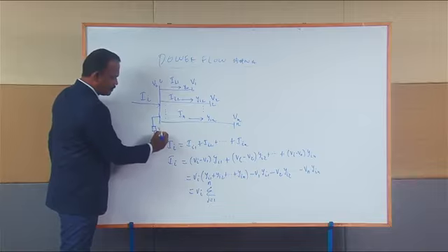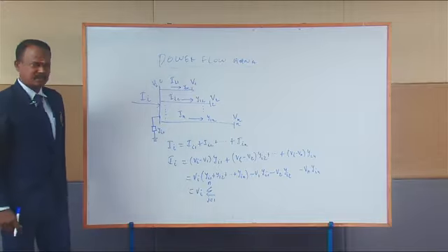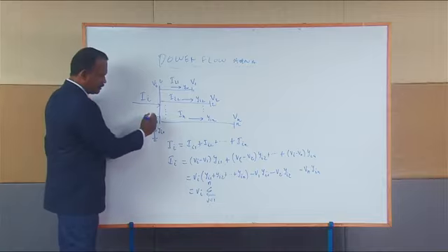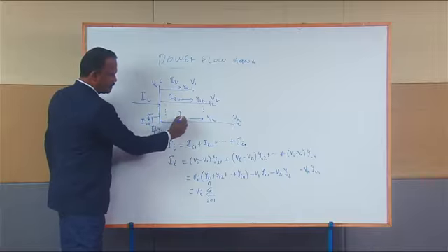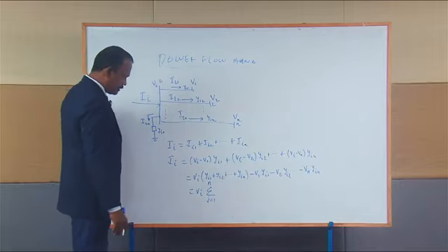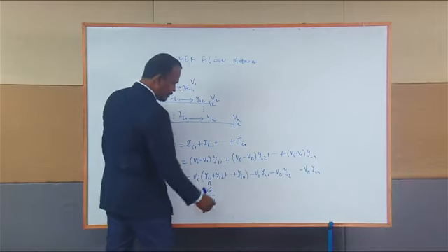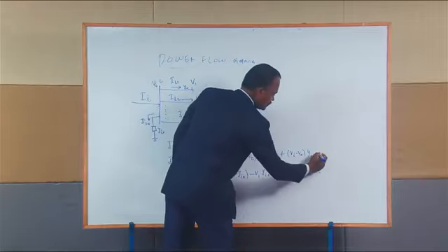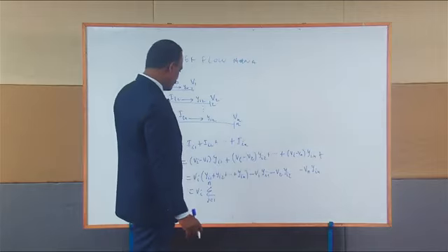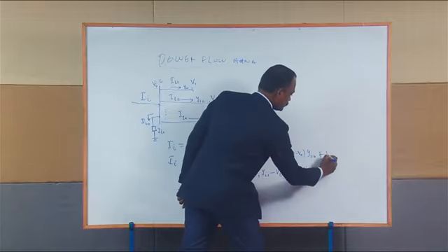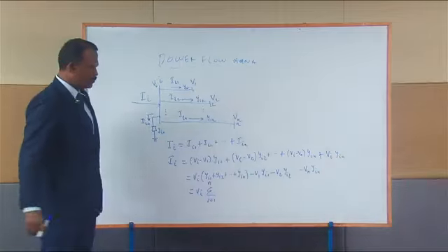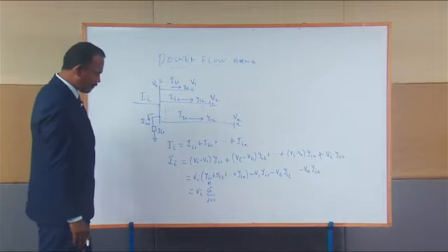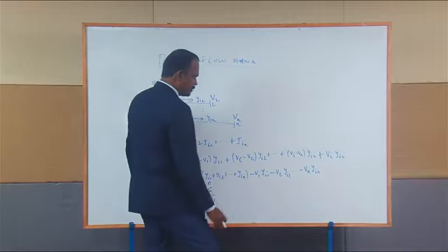Actually, in this diagram we can also include the self admittance of the network. Let us consider the self admittance of this line is yi0, and the current flow in this line is Ii0. Then I'll add one more term here so that this equation will be complete. So this is Vi into yi0, am I right? So I can include that term here.